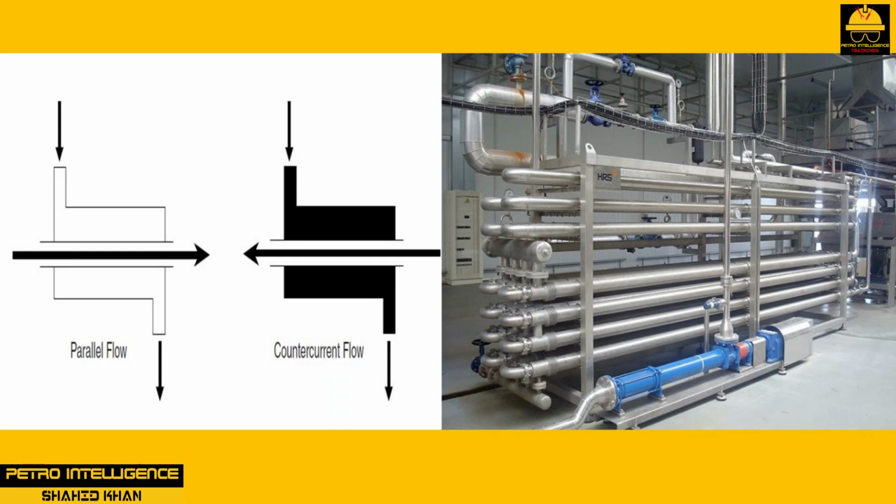Less heat will be transferred in a parallel flow exchanger because of this reduction in temperature difference. Static films produced against the piping limit heat transfer by acting like insulating barriers. The liquid close to the pipe is hot, and the liquid farthest away from the pipe is cooler. Any type of turbulent effect would tend to break up the static film and transfer heat energy by swirling it around the chamber. Parallel flow is not conducive to the creation of turbulent eddies.